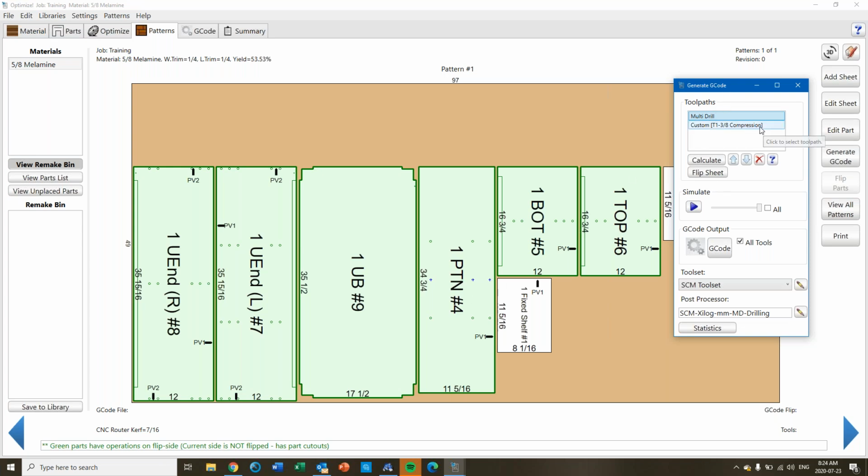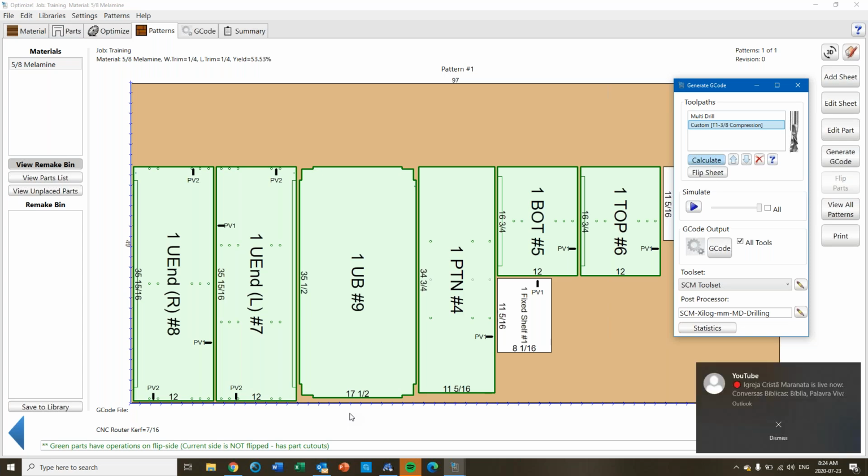And then it's going to do what's called a square and cut. It really doesn't take anything off. It just makes sure that when you flip it over, the width of your machine is right. This one really doesn't take any off, but it makes sure that your melamine or plywood is actually 48 or 48 and a half or whatever you're saying it is. It's just going to verify that. And then you're going to flip the sheet over.